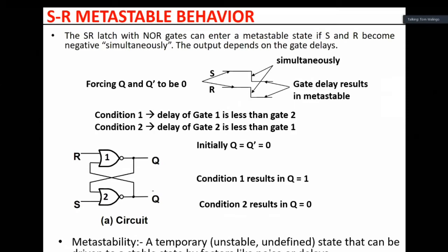So you don't want such situations in a circuit. You cannot have a chip or gates with the same propagation delays. They will definitely be different. So you don't want a situation whereby you don't know whether this Q is a 1 or 0 depending on propagation delays, when some hazards in the circuit happen. So these are metastable states and we don't want them.